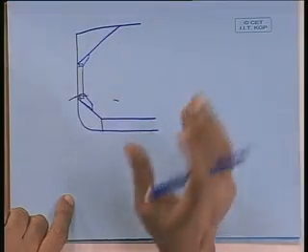The thing is that when you are carrying any solid material in a loose condition, this corner cannot be cleaned properly, whereas it does not stick here, but it can stick here into some sort of joints or knuckles there. The area is dark, and therefore, if the inspector or surveyor goes there, he can't see it properly and can't make out whether the thing is properly cleaned, or even for the structural aspect, the welding aspect, he can't find it out.